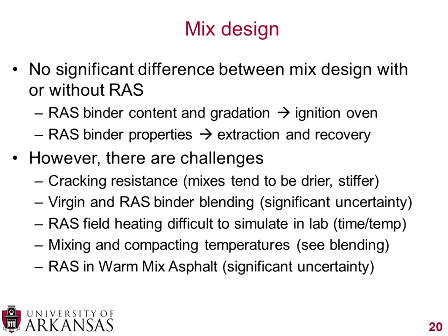And if you have a fully blended asphalt cement, that would give you a much different mixing and compacting temperature than if you had the virgin asphalt cement with some, you could almost say, larger clumps of the RAS binder that's not fully mixed into there.